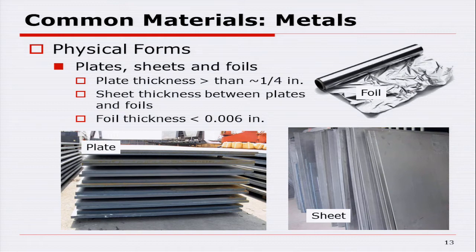Now, when you specify it, I don't have the thicknesses with respect to their gauge number, and maybe I should put it on here. When we order steel and sheet stock, we order by gauge. I'll call up and say I want 16 gauge, I want 14 gauge, I want 12, 10, 7 gauge thick steel. And 7 gauge is very close to 3/16 of an inch. When we talk about 10 gauge, we're talking about something that's close to 1/8 of an inch.